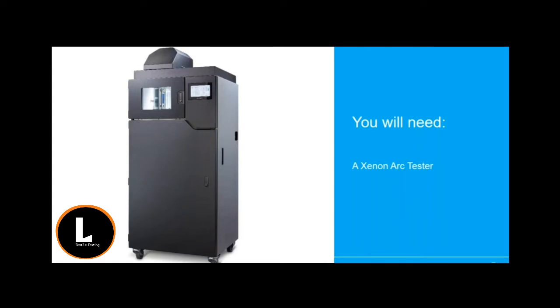With your xenon arc tester, you would expect to get specimen holders or KG1 filters, the xenon arc lamp itself, and a black standard thermometer as favoured by ISO, with the option of a black panel thermometer as favoured by AATCC. It's recommended that the instrument is kept in a climate-controlled laboratory setting.